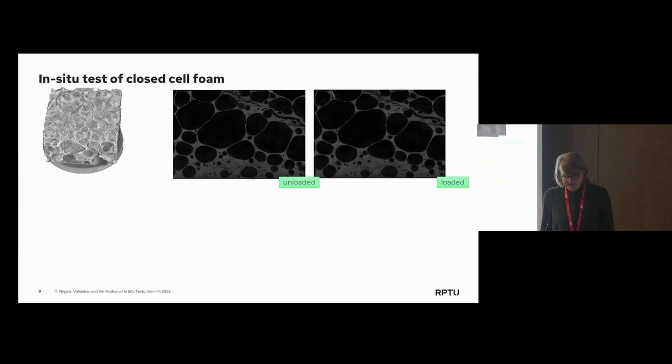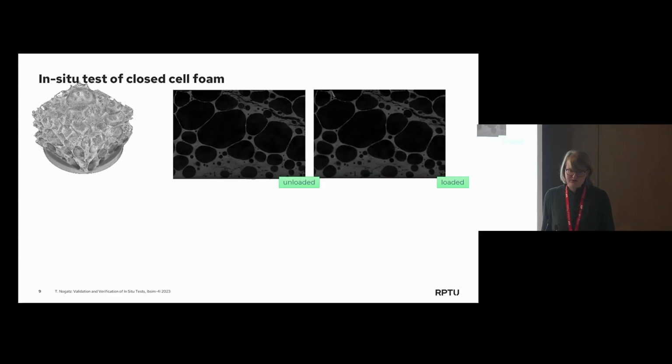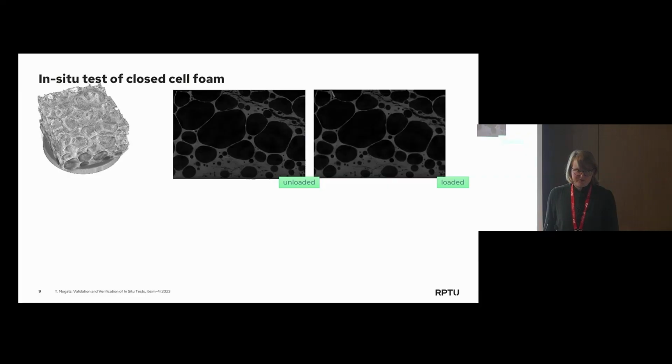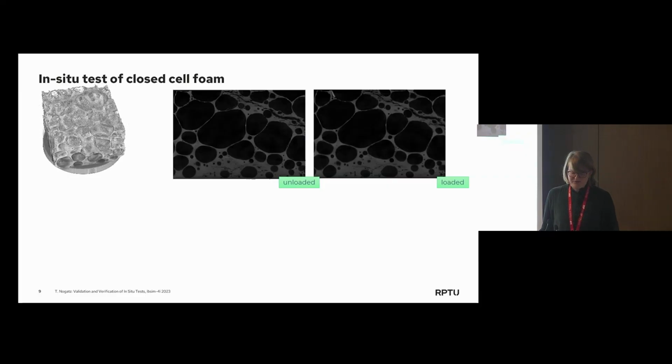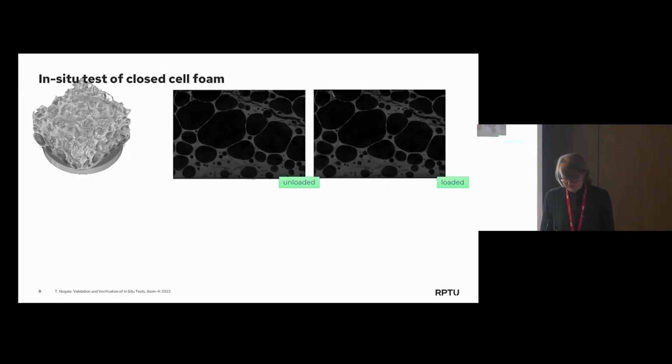And that is the content of the next example, because here we have an aluminium foam, or again a foam, but this time also very challenging because we have very thin struts and very large voids. These are usually the materials where you really struggle to find a proper local DVC, for example. So I think global usually performs a little bit better, but then may overlook small motion. But when you, for example, in local DVC put a subvolume exactly in the void, well, what would you do? Nothing at best, and not converging or not putting out any solution at worst.